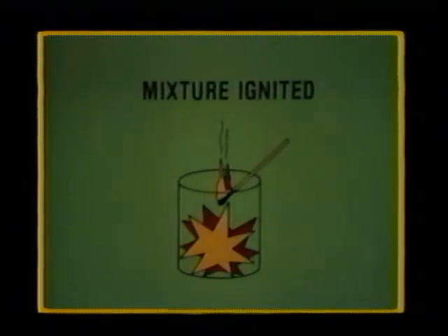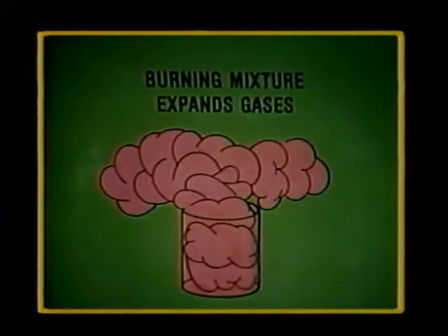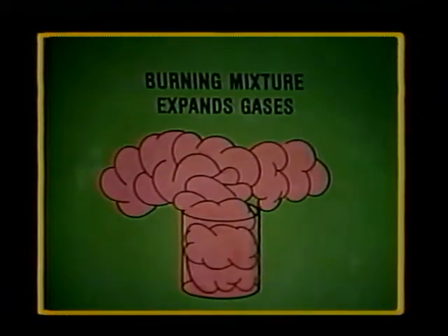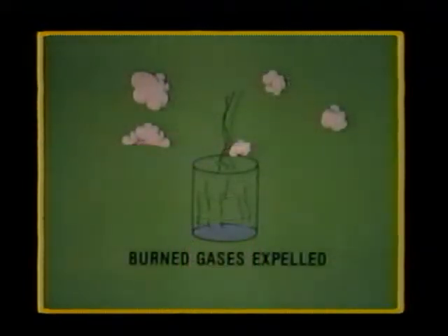This compressed mixture is then ignited and burned, releasing energy in the form of heat. The air inside the engine immediately absorbs this heat and expands to many times its original volume. It is this expansion that is converted into mechanical power. Finally, after the energy has been extracted from expanding gases, these gases are expelled from the engine, and the cycle is ready to begin all over again.